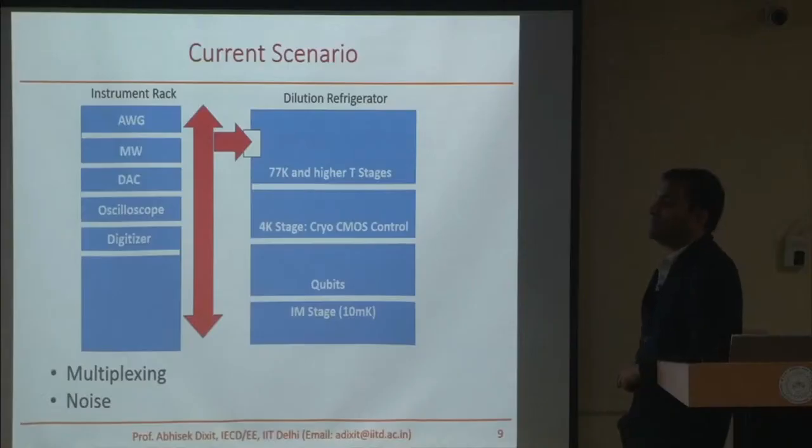And one more query. We were looking at these anomalous trends in the subthreshold swing and the threshold voltage at cryo temperatures. Many people have explained it using very high interface states, 10^14 per centimeter square, 10^13 per centimeter square. Do you really observe those values in modern transistors, or are they just used for modeling purposes? No, there is substance to it.